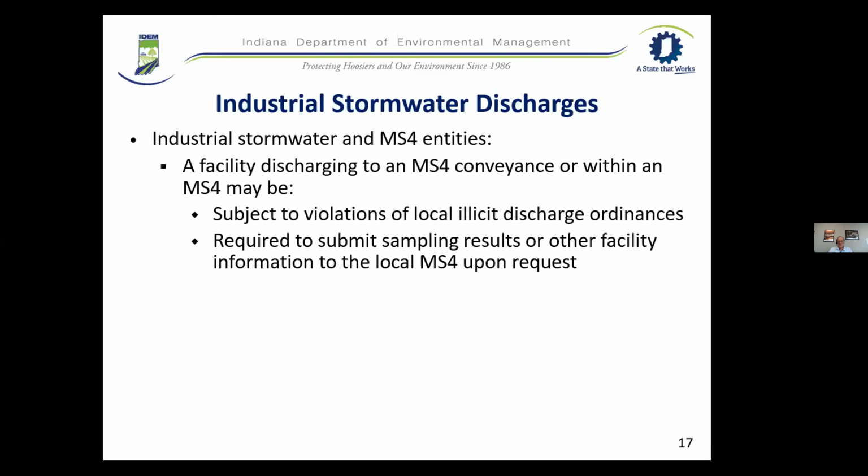ordinance. So I think it is important to know that you are not only working to comply with IDEM stormwater regulation for industrial discharges, but you're also subject to any local ordinance through this MS4 illicit discharge ordinance. And as I said, if you get contacted by an MS4, oftentimes they'll contact us, but feel free to reach out to the IDEM stormwater program also, and we can work with the MS4 and you to work through the situation.